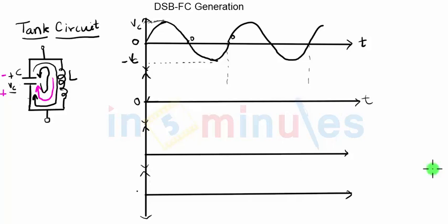So if you consider any practical circuit and observe the voltage across the capacitor or inductor, you will get sinusoidal oscillation, but of reduced amplitude. After a point of time, the sinusoidal oscillations will decay to zero. Please note that the waveforms are not drawn to scale, especially in terms of the frequencies we are showing.